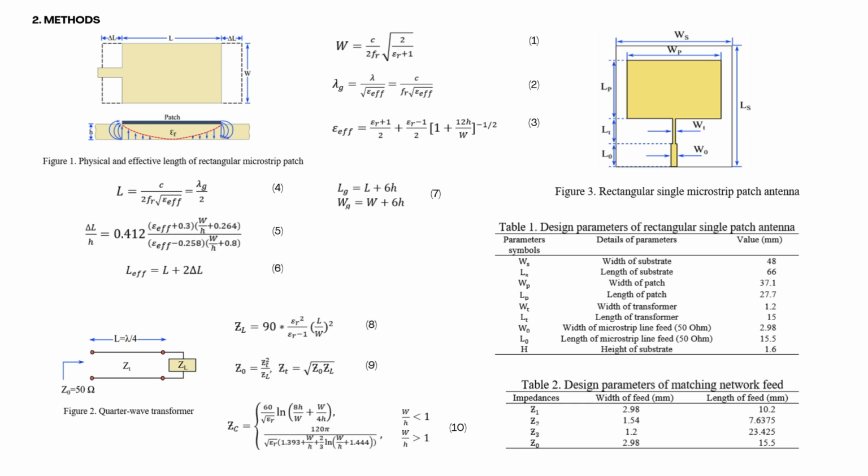However, as radiation doesn't emanate from the center, but rather from the region between the edge of the patch and the grounded surface, the phenomenon referred to as the fringing effect arises. Consequently, electrically, the patch appears longer than its typically calculated length, giving rise to the concept of delta L, which represents the extra electrical length. It's shown in figure 1.